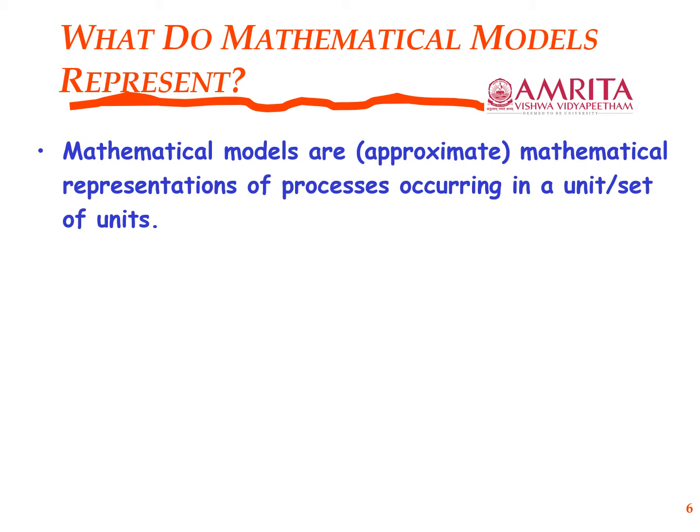And therefore when we write that the total mass is conserved, the species are conserved, and the energy is conserved, yes, they are conserved, the conservation is exact, but we partition the total energy into those assigned to different streams. We say that the vapor stream leaving the tray has a certain enthalpy, the liquid stream leaving the tray has a certain enthalpy, the vapor stream entering the tray has a certain enthalpy, the liquid stream entering the tray has a certain enthalpy.